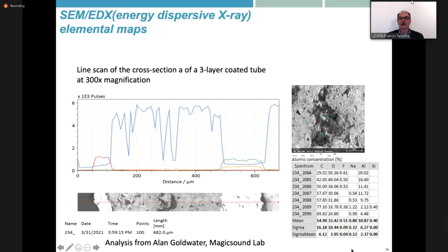In the graph in the upper left, which aligns with the SEM image in the lower left, the red line designates the nickel composition, the blue line the aluminum in the dielectric, and the green line the copper coating. The voids in the image line up with the reduced aluminum strength in the graph. There is obviously some sodium impurity, yellow line, in the copper.